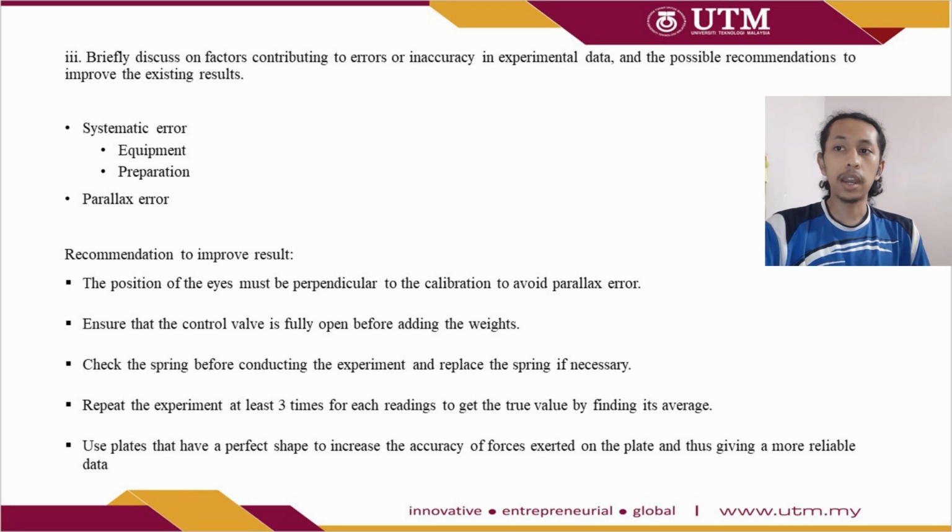There may also be errors in calculating due to the uncertainty in the measurement, as well as mistakes made during calculating the results, or errors during the preparation of the apparatus. For example, we make sure no weight is placed on the lever mechanism of the deflector when setting up the equipment.